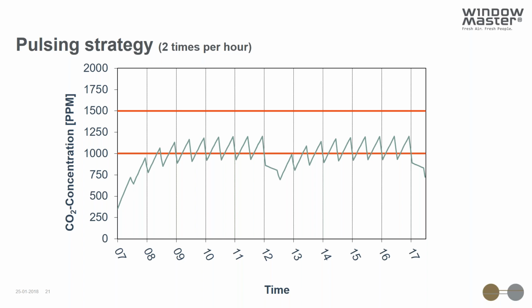And you are not really going to have any draft problems when you're only ventilating for 3 minutes. It would require longer exposure to cold air, even if it's 32 degrees outside.